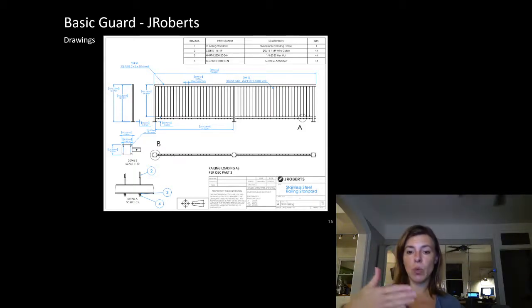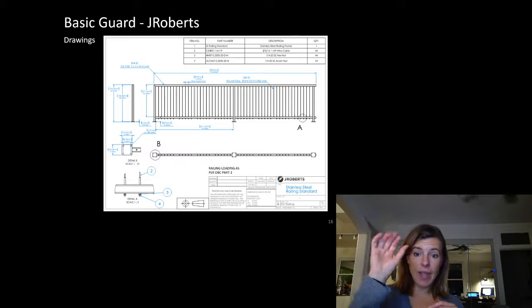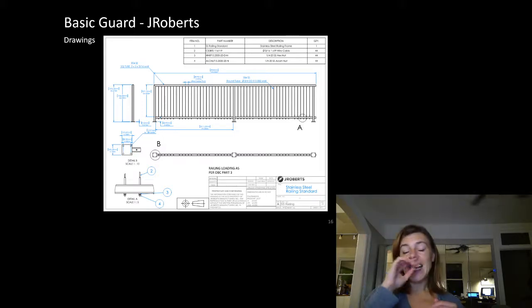It was more of a visual divide. People would probably lean on it. But it didn't need to meet the requirements of a guard. But what I decided to do was say, okay, there is no criteria really for this, but maybe handrail criteria. So I made the choice to design it as a guard with them, because they already had, actually, I believe it was already built.